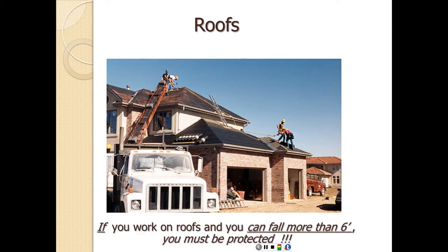If you work on roofs and you can fall more than 6 feet, you must be protected. So here we have definitely above 6 feet. It seems that we have a PFAS here. Whether it's properly tied or not, it doesn't appear from the picture, but that might be okay if it's properly tied.